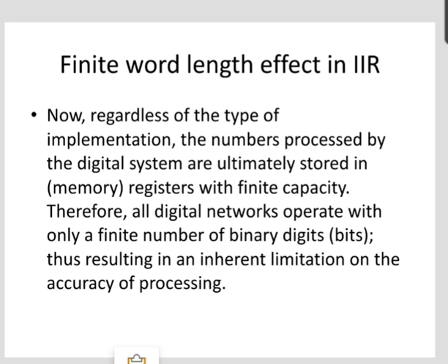In the realization of FIR and IIR filter, in hardware or in software on a general purpose computer, the accuracy with which the filter coefficient can be specified is limited by the word length of the computer. Since the coefficients used in implementing a given filter are not exact, the poles and zeros of the system function will be different from the desired poles and zeros. Consequently, we obtain a filter having a frequency response that is different from the frequency response of the filter with unquantized coefficients. Also, it sometimes affects stability of the filter.